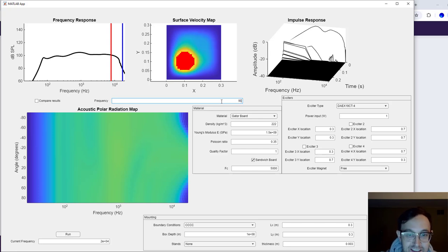Yeah, as you can see, the low Q keeps the vibrations from pretty much spreading. There's no modes anymore or anything. Yeah, it's just immediately, I mean, this is more or less just having a piston loudspeaker, which has an omnidirectional frequency response up to a certain beaming wavelength and flat frequency response.